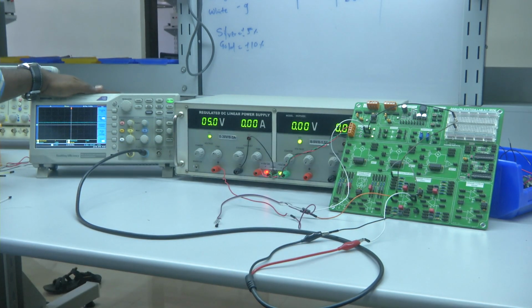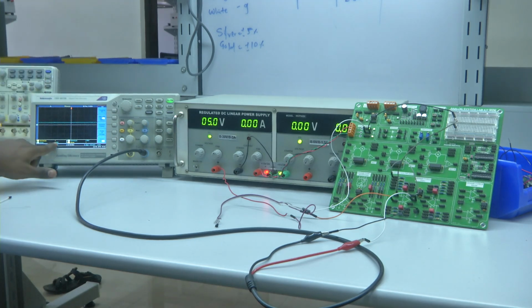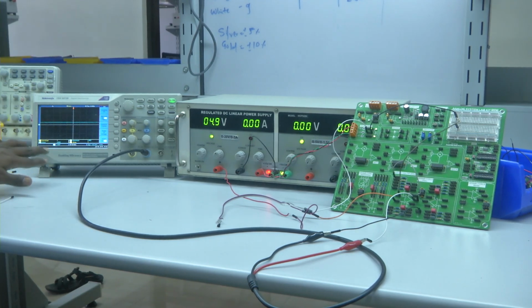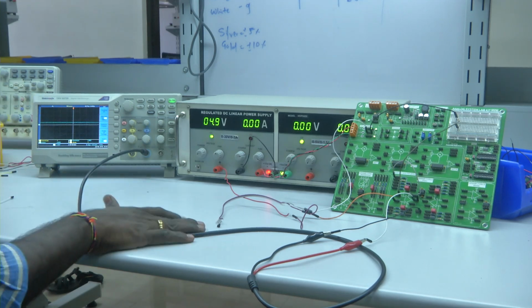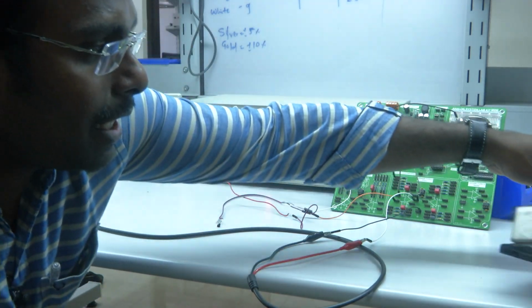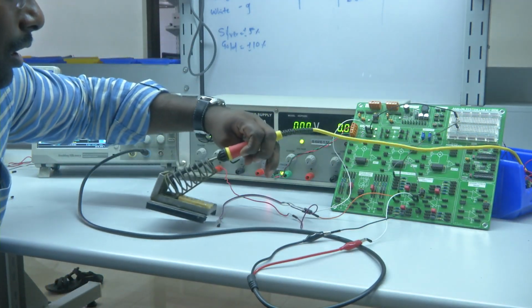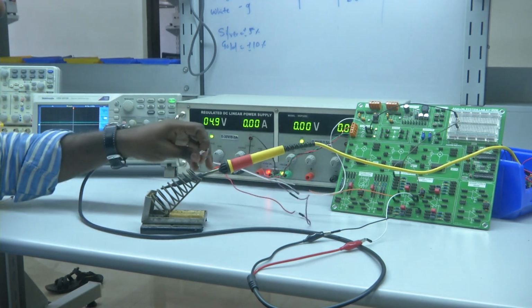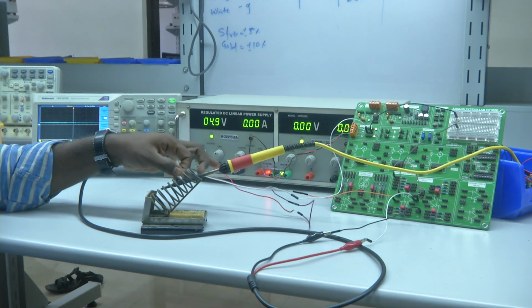If you recall, the room temperature that we measured was close to 28 degrees. Now the mean value is showing 2.6 volt. Previously it was 2.8, now it is 2.6. The difference is because of the difference in the gain. There is an error of 2 degrees, but let us observe the working of this LM35 by just probing and touching it to the soldering station, to see whether we get the same temperature or not.